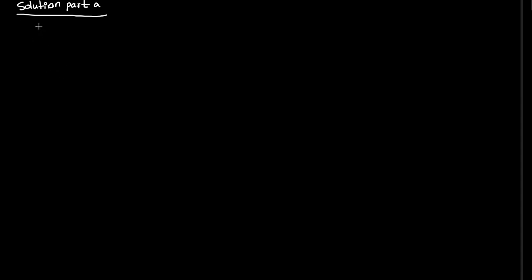So the first thing here, at steady state, VA can be written as equal to EA plus IA RA. So this will equal K phi omega plus IA RA. Now let's see, K phi is given, N is given, and K phi actually is 0.1 volt per RPM, so this will be K phi N. So this is given, and the current is also given, and this one is given. So it's plug and play.